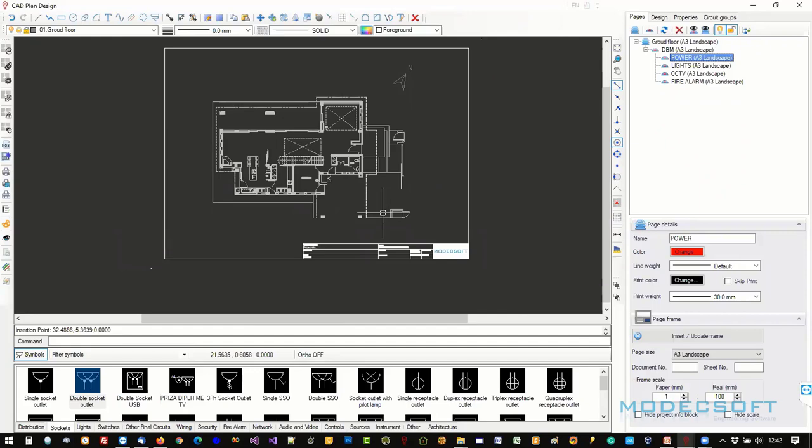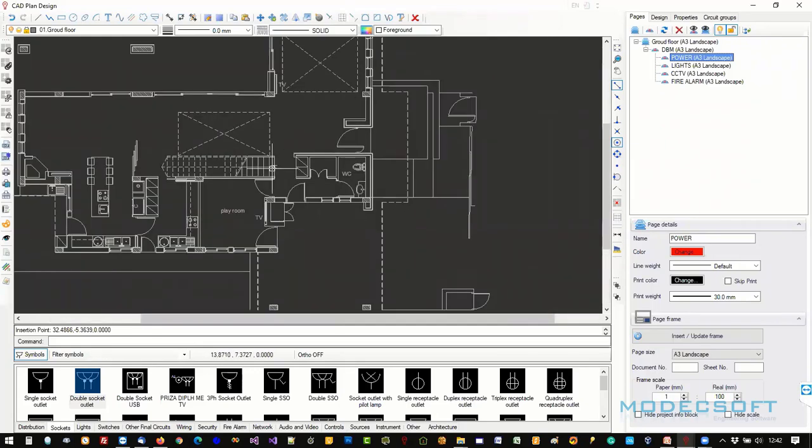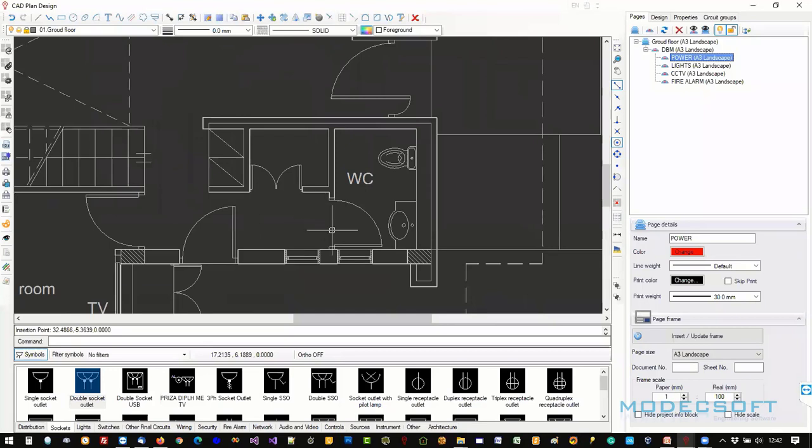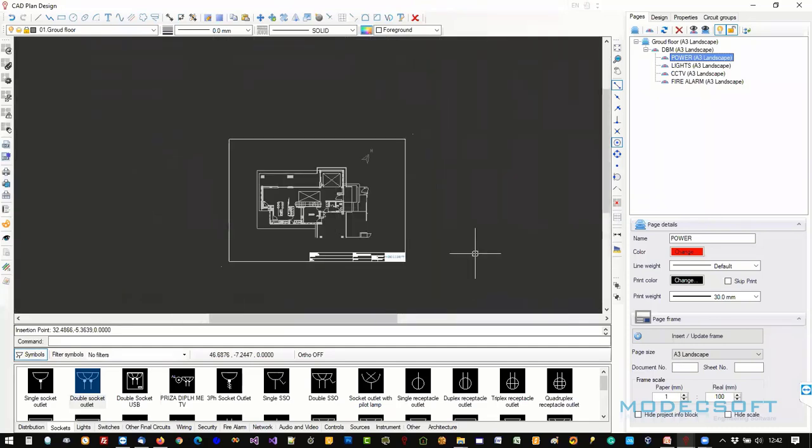Now, in regards to the scale, because it might be a confusion here. When you want to scale the drawing, you don't scale the actual figures, the actual symbols, or the actual references. You don't want to do that because you're going to lose the measurements. The measurements need to be in meters all the time because we want to get the measurements from the wires. So if you want to print with a different scale, what you are scaling is the frame.